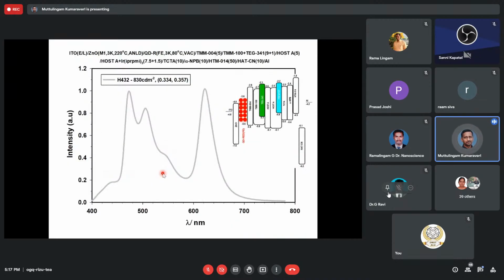This is some lighting work we have done at Brunel. We use quantum dots. There are 3 primary colors, so we need 3 stacks. I'm going to talk about the structure of this lighting panel later. Here we use zinc oxide as a solution process, and red quantum dots we used with spin coating fabrication, and all these others we used vacuum thermal evaporation. We could make a very good white spectrum.